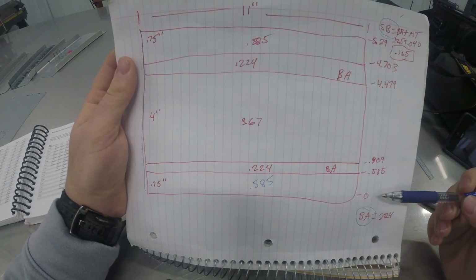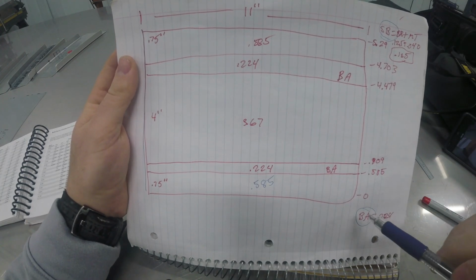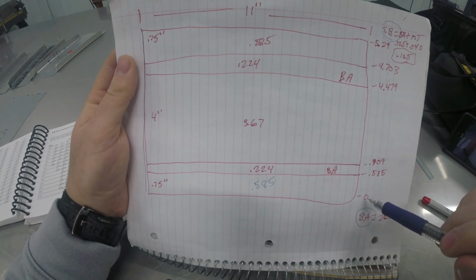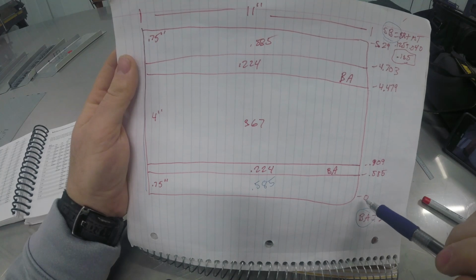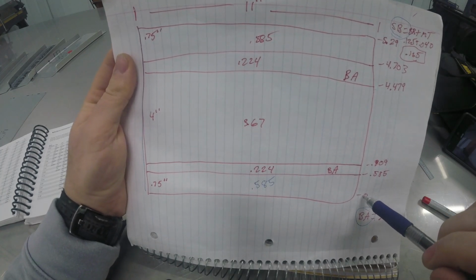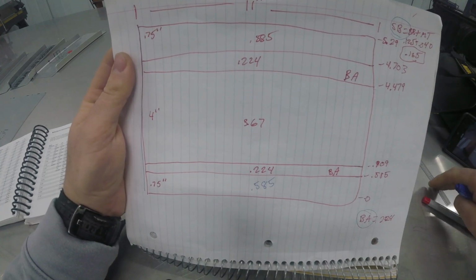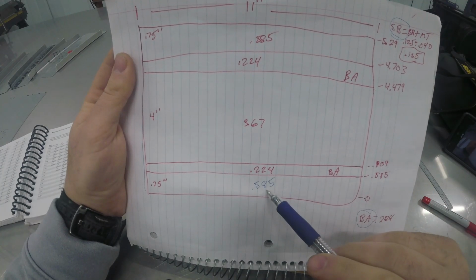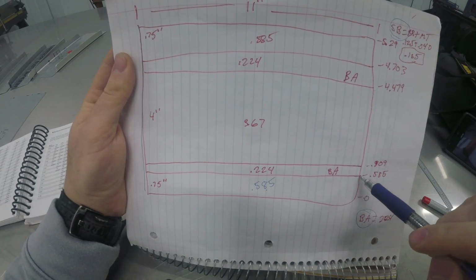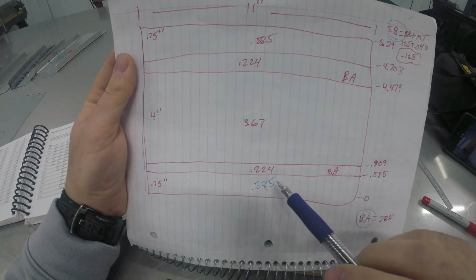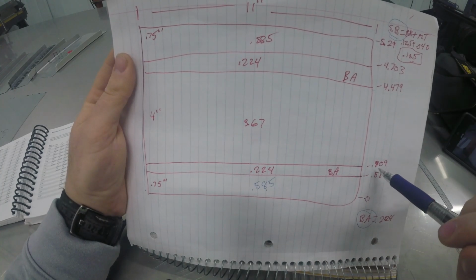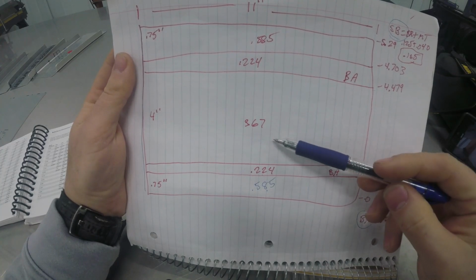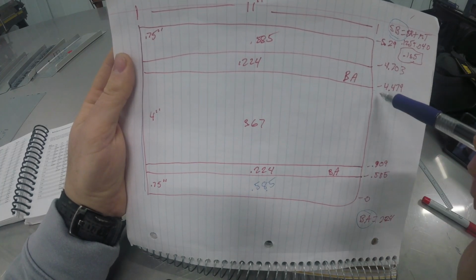Then on the very right hand side, what I like to do is write out what my measurements are going to be here. So if the bottom of this piece is our 0 mark on our ruler, we're going to start with 0 there. We're going to add our 0.585. That's where our first mark's going to be. Next, we can add our bend allowance to give us 0.809. Next, we can add our big flat in and that'll put us up to our next bend.